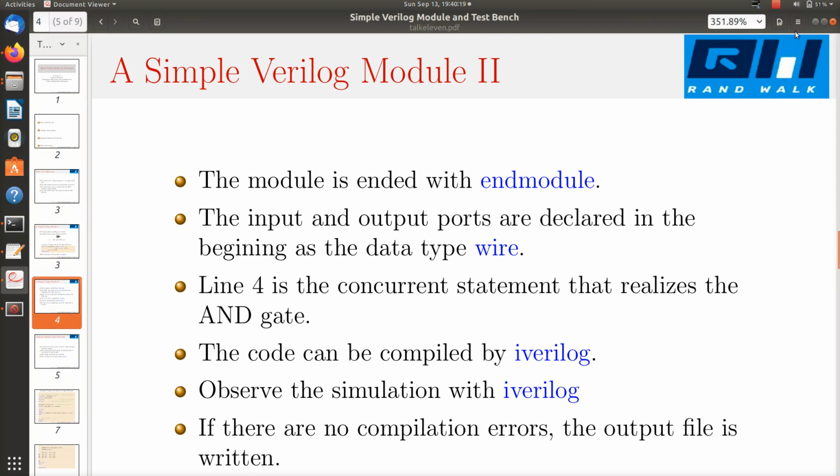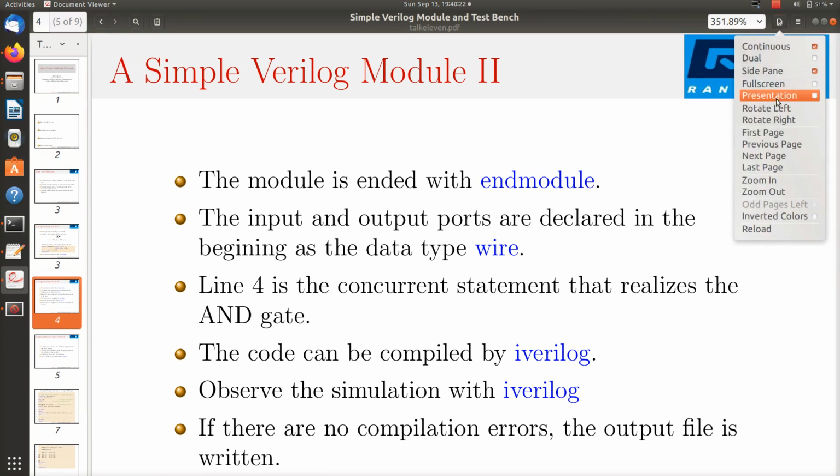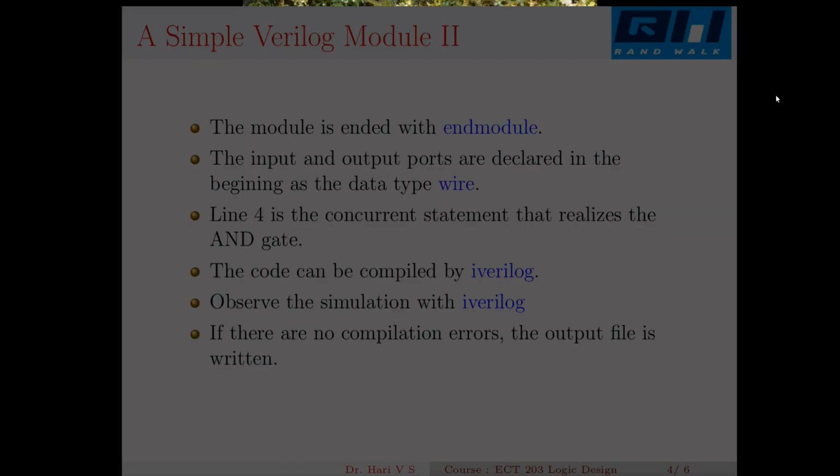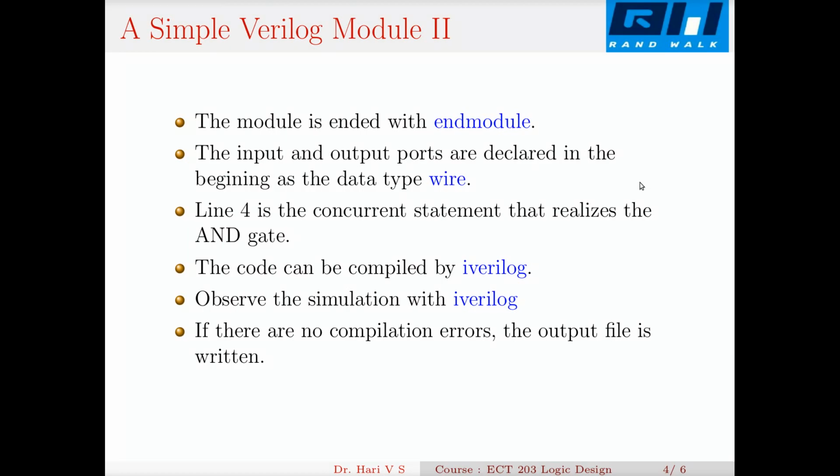Now this is not enough, because one way you can test is by writing it into an FPGA board, like a tiny FPGA. I can test with real signals that you may be able to do in the lab. But here what I do is I test it with a test bench. I write a separate program for that. I write a separate Verilog module for this and test with the test signals.